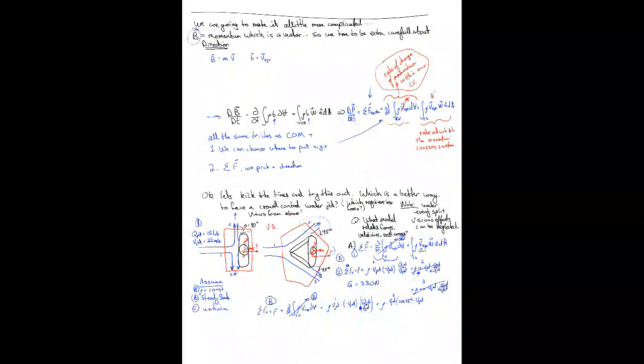Now, I want to point out a mistake that a lot of people make when they get in a hurry. If you look at the first term for our exit 1, you can see that it's rho v jet times negative v jet times q jet over v jet. So we can often write this as rho v squared times A, and they'll just do that. And they'll do that for this term here. They'll do v jet times the cosine of 45 squared, and that's not right, because our w dot n hat is not multiplied by the cosine of 45, just our vx. So it's easy to make that mistake if you're in a hurry.